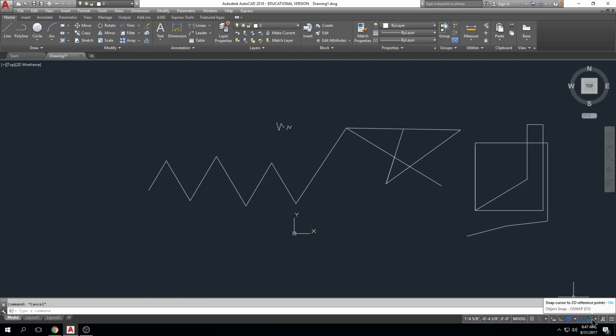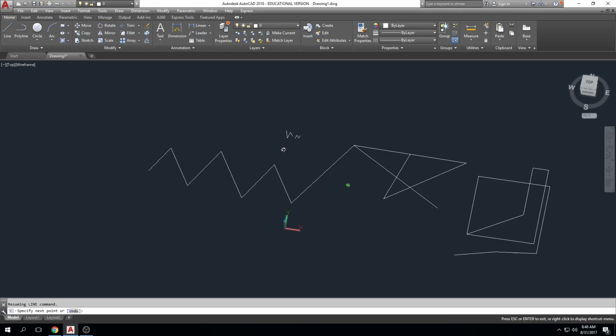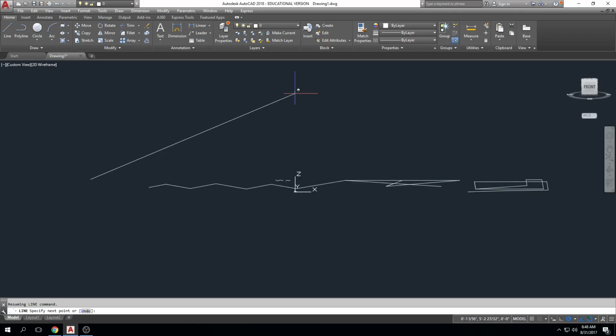Well, here's the thing with Shift. Shift in AutoCAD, right? So I'm in the line command and I click and I press Shift, right? Which you're in dynamic input, which is a little different. But the problem with Shift is that if I am drawing, so yes, right? I get an ortho. Did you see that? But the problem with Shift is that if I hold it and I accidentally pan a little bit, it will pop me into 3D.